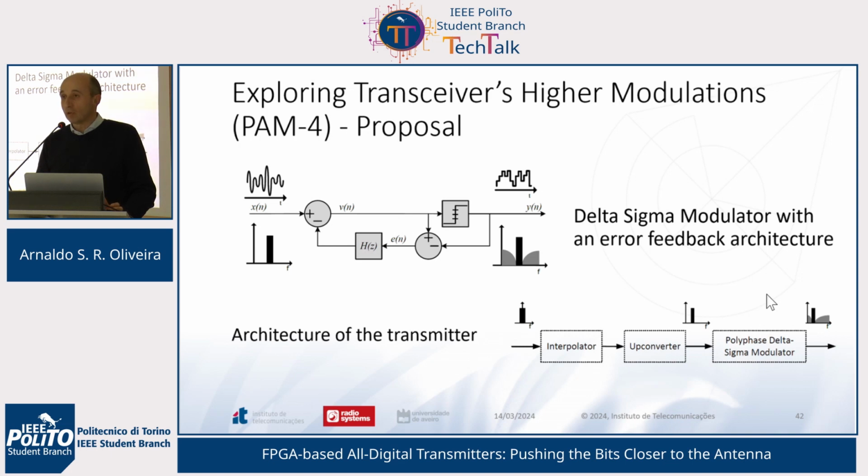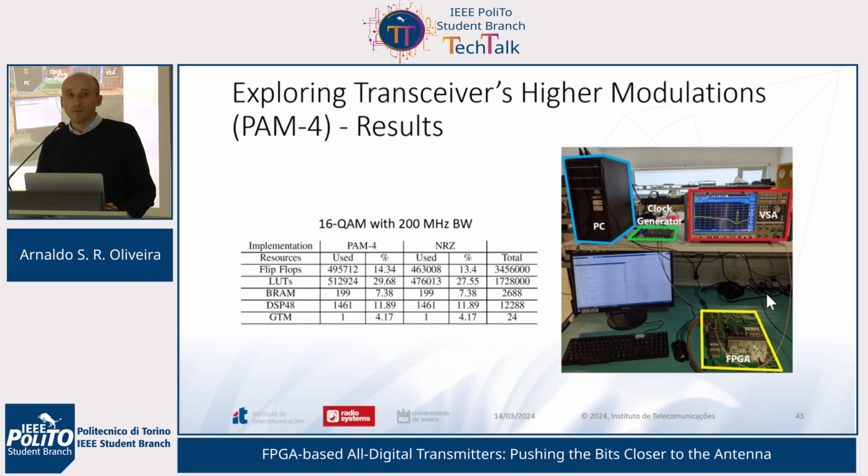All the remaining blocks will be kept the same, which means that in terms of logic resources, if we compare a non-return-to-zero, so a non-PAM4 transceiver, with a PAM4 transceiver, we basically have nearly the same resources. The percentage of flip-flops, lookup tables, DRAMs, DSP slices, and the number of transceivers is basically the same, because we are benefiting just from the 4-level output of the transceiver.